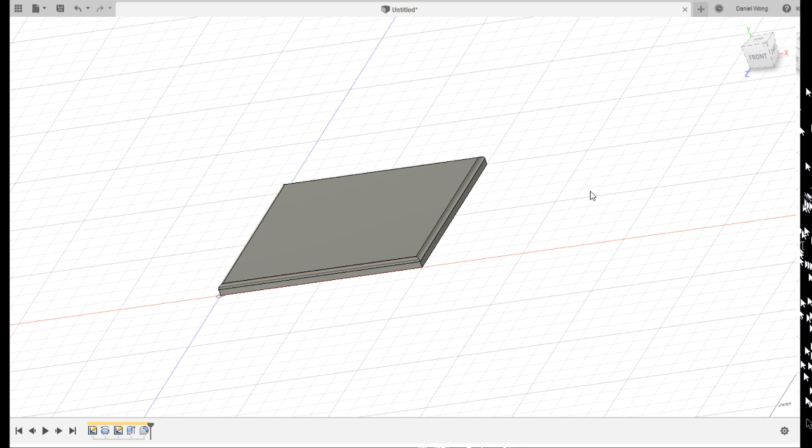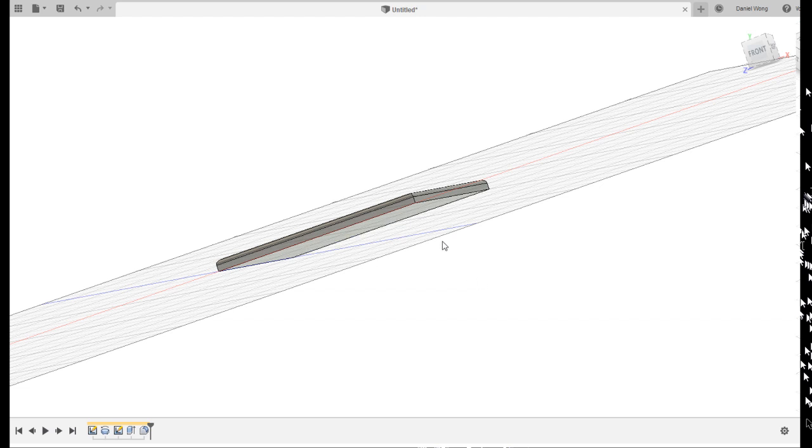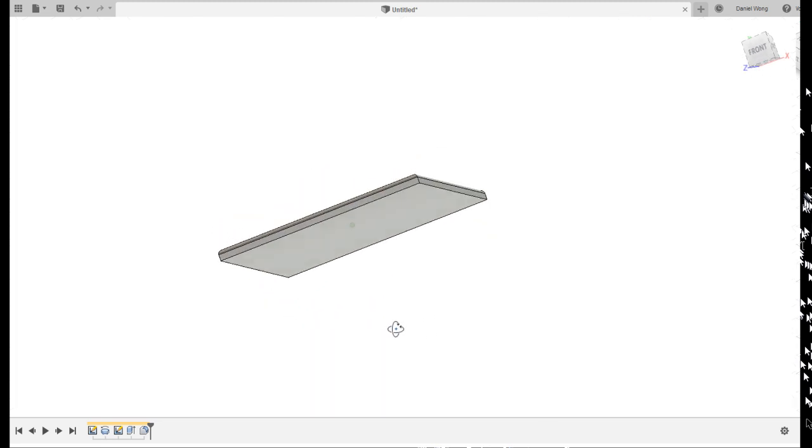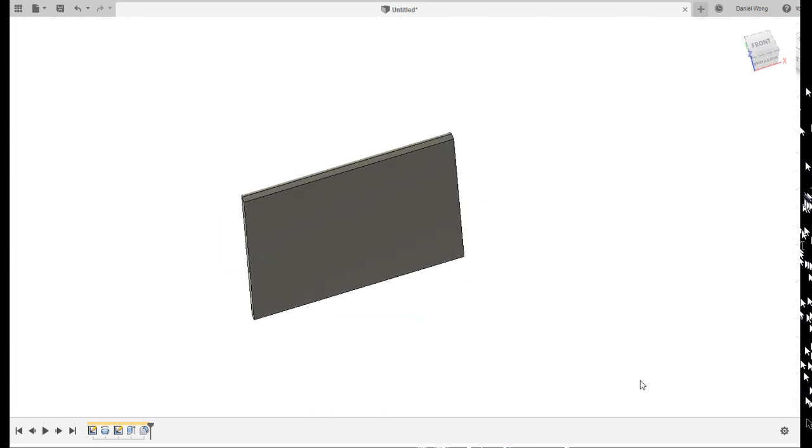Okay. Great. So now we're going to put a 3mm chamfer on the base edges of this. What might interest you, by the way, is to remove the layout grid in the viewports menu here, because we don't really need that layout grid anymore. When you open a sketch, it automatically previews a layout grid, so you don't need to worry about that.